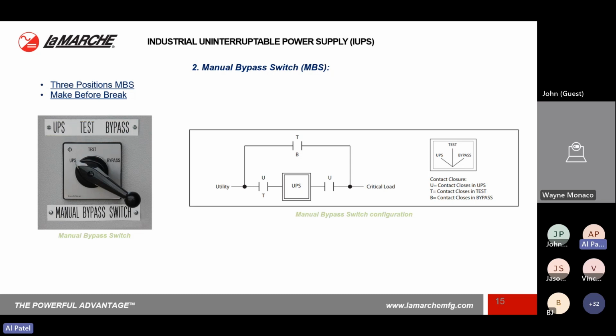The reason for this is you can go ahead and actually do your testing or servicing, making or troubleshooting the UPS while the load is not affected. The bypass is basically a complete bypass from the utility directly to the load. Bypasses the UPS.